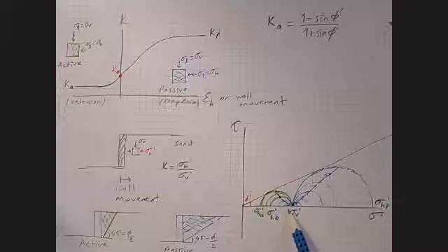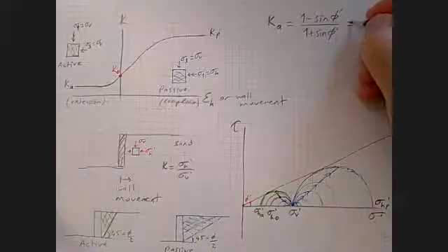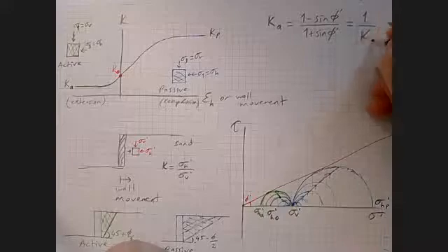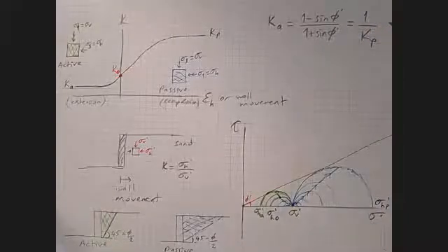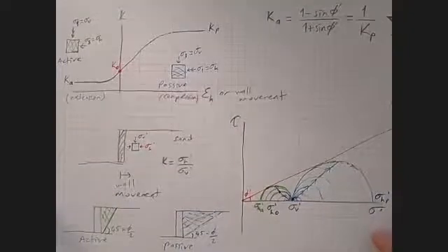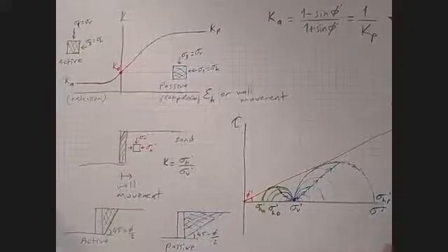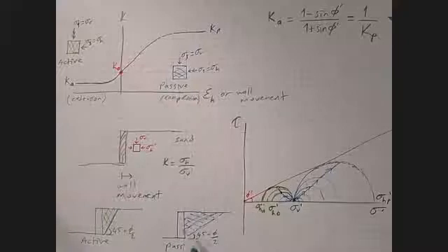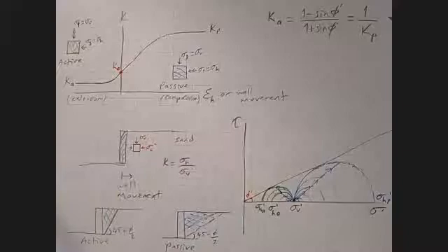So that for the active case and passive case is the same problem. Therefore, very simply, Ka and Kp are inverse of each other. So based on this, now I can calculate what my horizontal stresses are at failure due to horizontal straining, as well as at rest conditions.